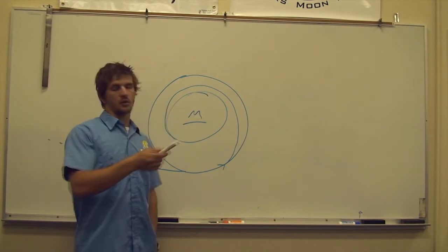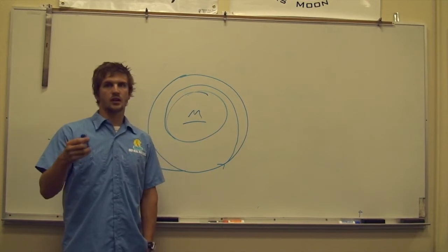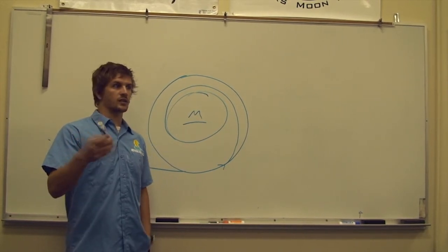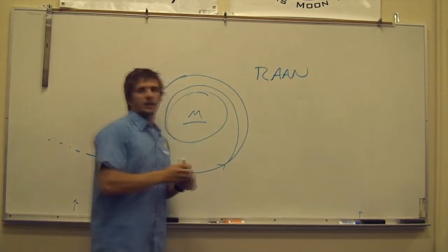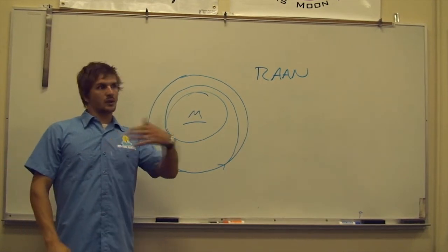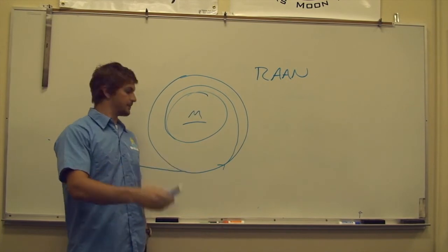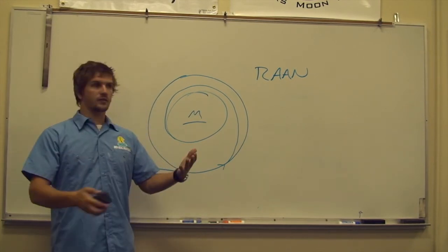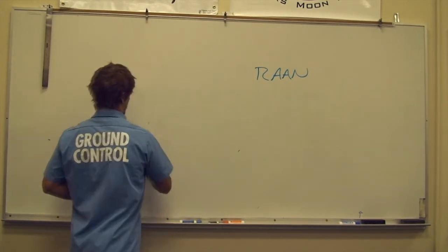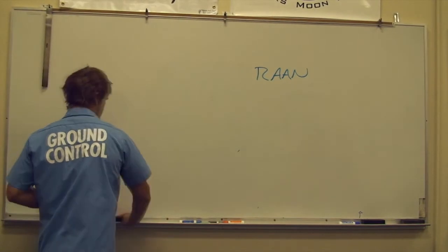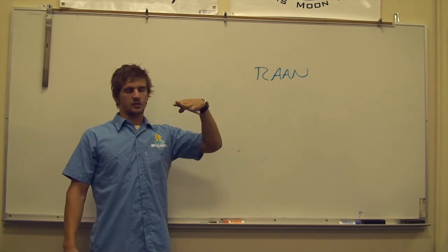For the lunar parking orbit method, however, this is a little bit more involved. In the parking orbit method, you have a right ascension of the ascending node, as you remember from earlier. And again, this is relative to the Earth-Moon line, and it is going to be based on your time of flight. For a better visual, I will show you how time of flight affects your right ascension. As your time of flight is lowered, you're essentially going to move your trajectory closer